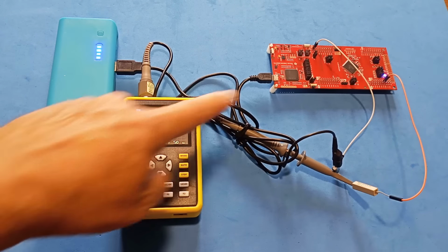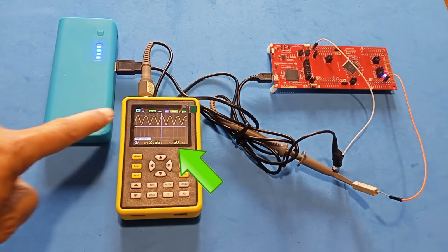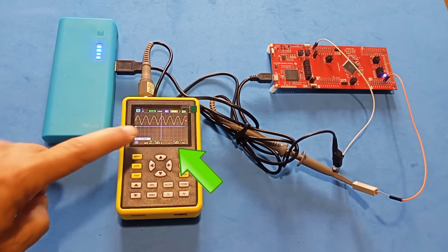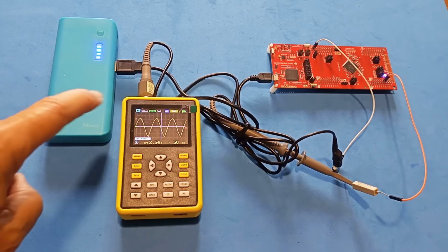As seen in the working prototype, the system generates a sinusoidal signal at a frequency of 50 Hz, as specified in the project. The waveform is very good, but it only exists thanks to the RC filter, since the MCU is not generating a true sine wave but rather digital signals.